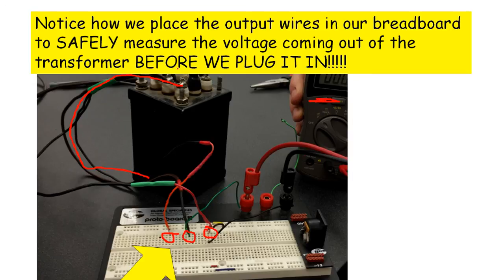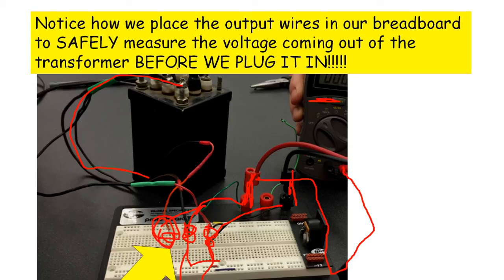Okay, so we've got those 3 wires in our breadboard, and Michael has his voltmeter hooked up. The voltmeter leads are coming around and going into here. One end of his voltmeter is on this terminal, the other end is in the middle terminal. So he's measuring the voltage across the center tap and one end of the transformer. Then he's going to pick this middle one up and measure across the 2 ends of the transformer, and then pick this one up and go to the center again.